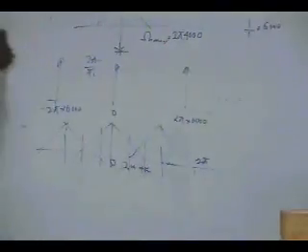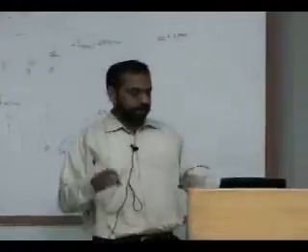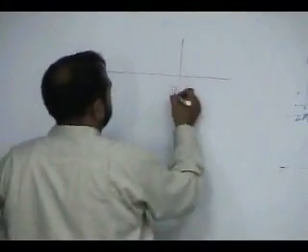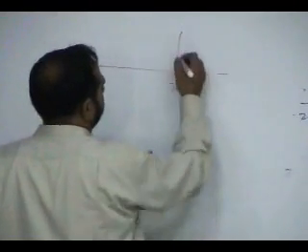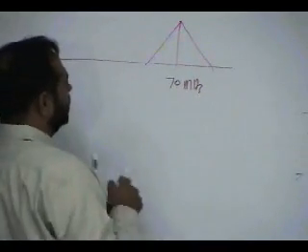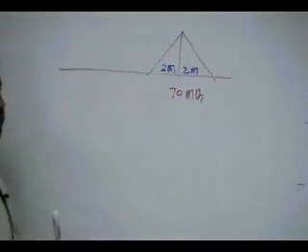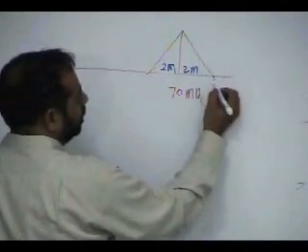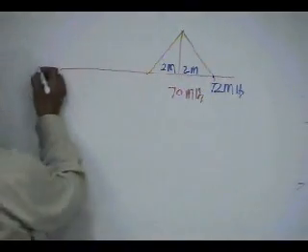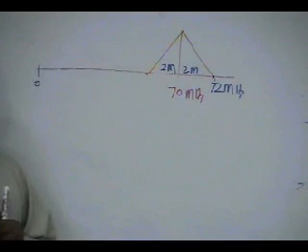For example, in digital communication, usually your signal is far out at some frequency. Let's say your signal is at 70 megahertz, and it is only a 4 megahertz signal. A 4 megahertz signal. Okay, so 2 mega here and 2 mega here. Now, what is the highest frequency? So, if you obey this rule, you need to sample it at what rate?